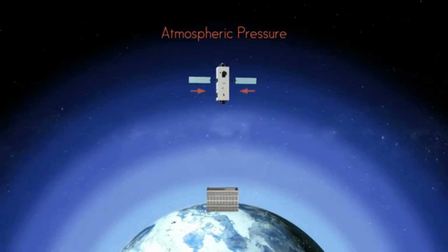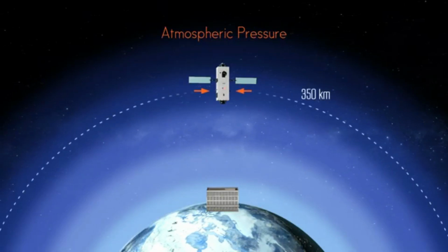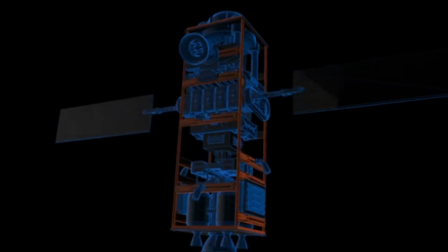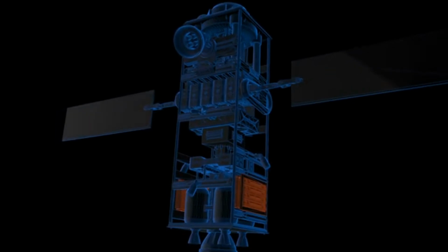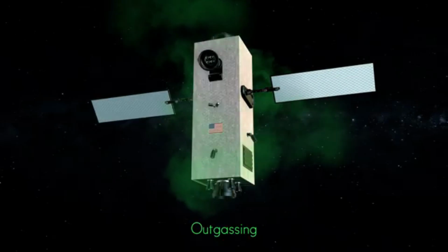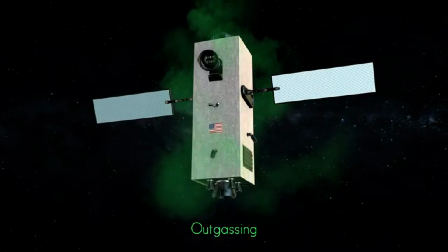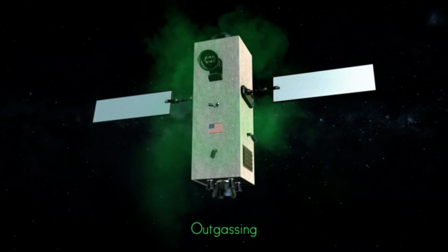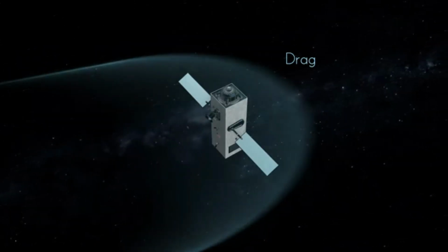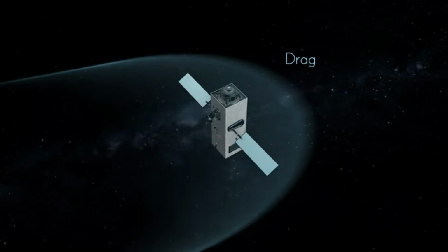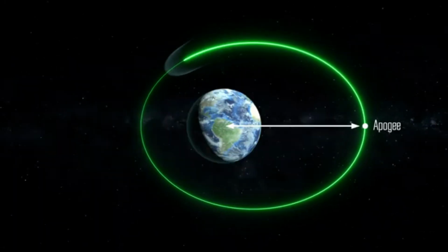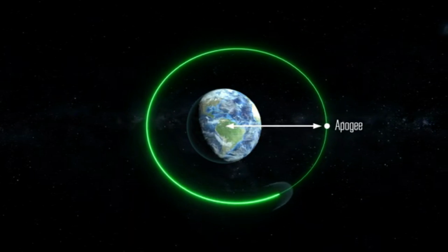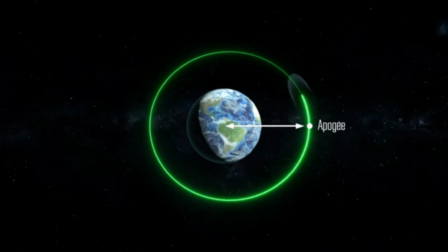Space environments are unpredictable. Forces like solar radiation pressure, atmospheric drag, and gravity gradients constantly push the satellite off course. The ADCS combats these disturbances using actuators such as brushless DC motors, or BLDC motors. These motors generate torque by rapidly spinning rotors, allowing fine adjustments to the satellite attitude while consuming minimal power. This hybrid control system, combining the precision of PID and the adaptability of fuzzy logic, enables satellites to operate efficiently in complex conditions. It's a breakthrough in satellite engineering, ensuring reliable performance for diverse missions across our ever-expanding ventures in space.